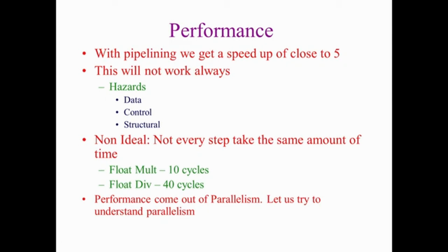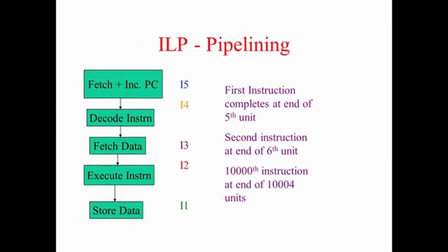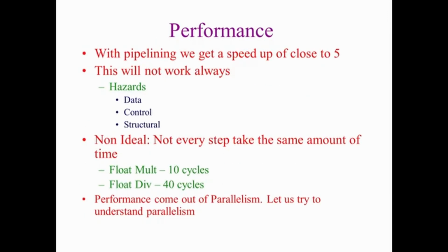This is one very important thing. So you will not have that free flow of instructions one after another. There may be reasons why I cannot proceed pumping that instruction from one stage to another, as we had seen in the previous slide. It may not be possible for I1, I2 to come at this same speed. Somewhere I have to stop them, and the reason for stopping is called hazard.